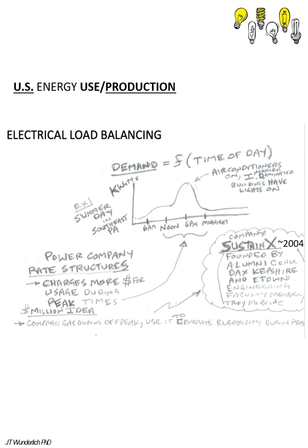We have electrical load balancing, and power companies have different rate structures, the rates of dollars that they charge you based on a number of things. There's a whole power factor thing I talk about in other lectures, where you have real and reactive power, and how you can put a bank of parallel capacitors in a factory to compensate for bad power factor due to the inductive loads of all the motors. That's a whole different thing. But we're talking about the loads here of actually on peak demand. You tax the grid and the generation, so it's bad for the grid, and actually you get a penalty for using electricity during peak times.